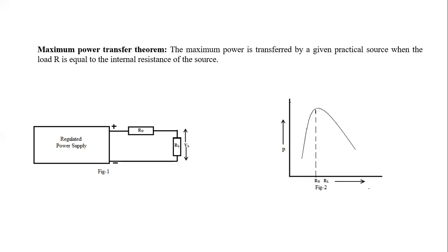If we can vary the load resistance, and accordingly plot the load resistance versus the load power curve, we'll get the maximum power. And at that maximum power, if we find the load resistance, we'll see that this load resistance matches the internal resistance, and that will prove the maximum power transfer theorem. Okay, I am telling again what we are going to do.